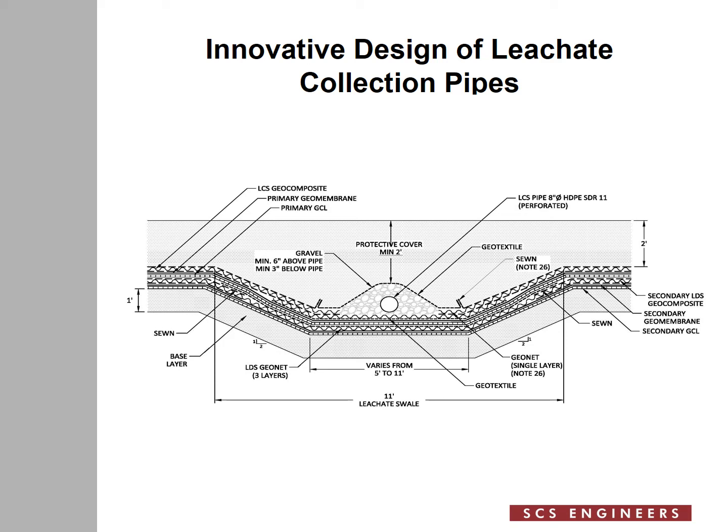The textile and the geonet both act as cushion to protect the geomembrane against the gravel that goes above the geonet. As presented here, gravel goes directly on top of geonet. What it means is that there will be no geotextile going under the gravel to enclose or encase the gravel entirely into textile.